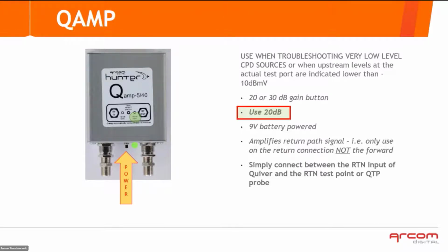When it powers down, it passes the entire bandwidth of the return and applies around 4-5 dB of insertion loss. So remember about it. If it powers down automatically, you may not see the peaks, or you will see them much lower. Make sure it's powered on and proper gain is highlighted when you intend to use it.